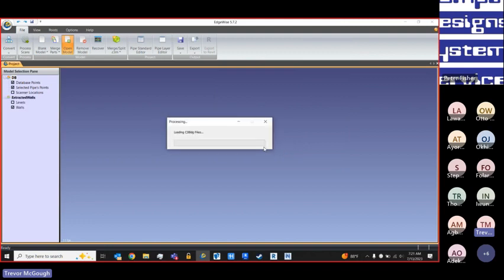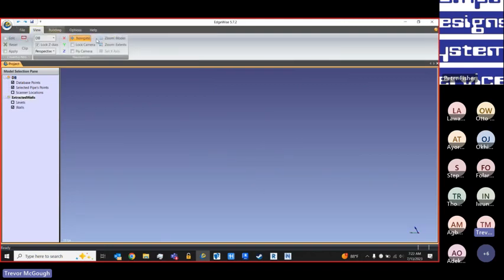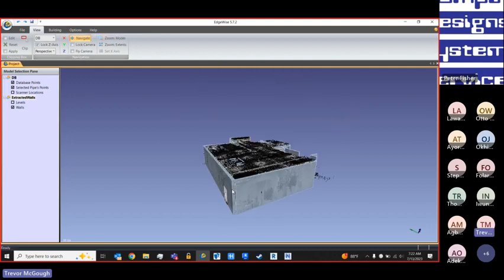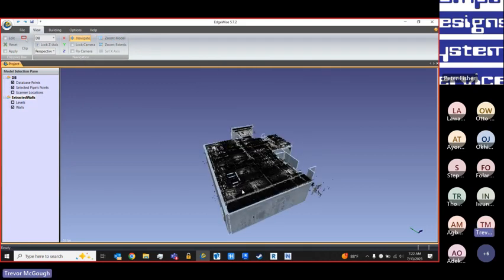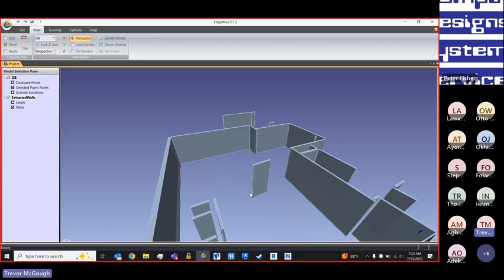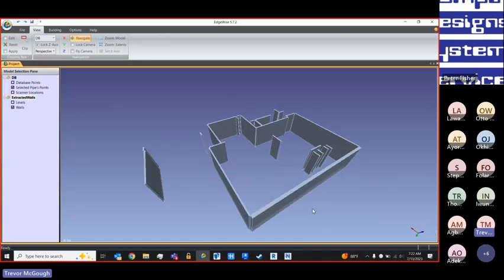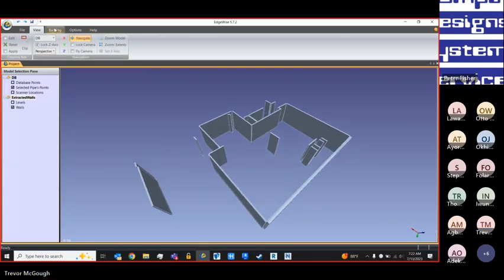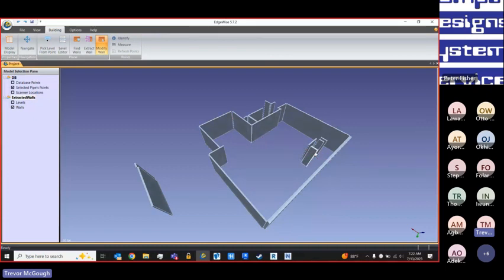So here's an example of the result of the automation for the building side of the software. It looks something like this. If I turn my point cloud off, these are the walls that EdgeWise has extracted. Once I have my walls created, I'll do a little bit of cleanup and delete a few false positives. In this case, things like doors, or some equipment that went floor to ceiling and looked enough like a wall.